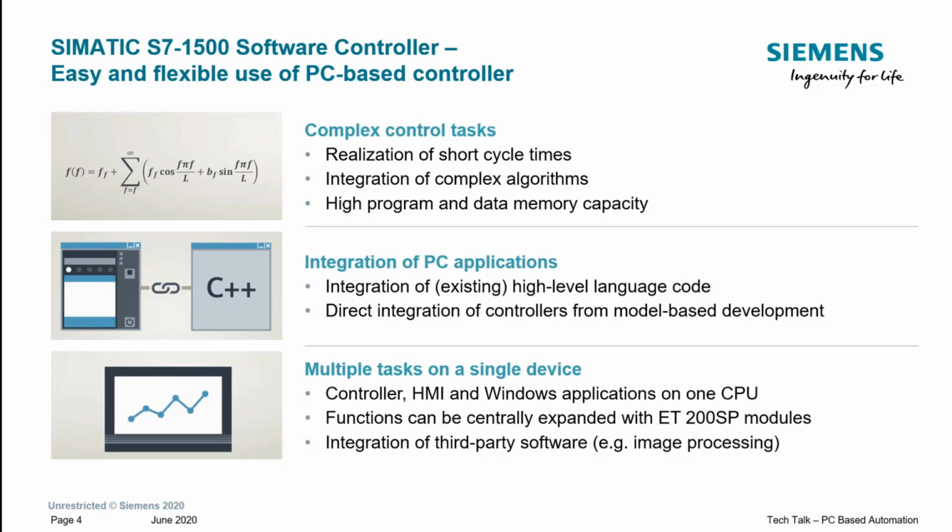Now we've got integration of complex algorithms. So this is referring to if we have maybe written some code in a language such as C to crunch some numbers. Maybe we're analyzing some analog inputs and we want to have an accept or reject signal being sent back. Instead of rewriting that code inside of SCL or anything else inside the controller, we can port the code that we've already written and put it into a function that can be called by these software PLCs.